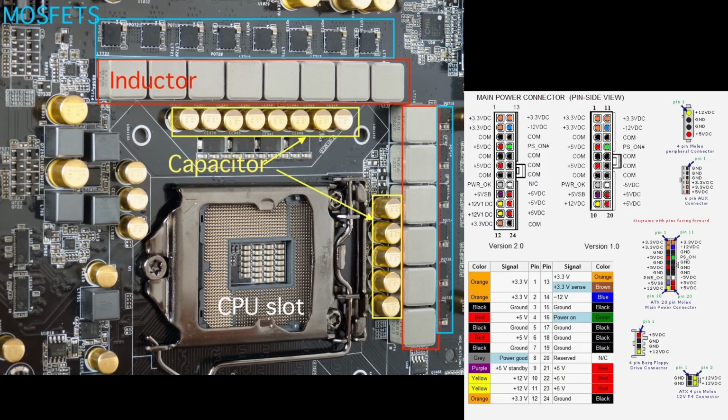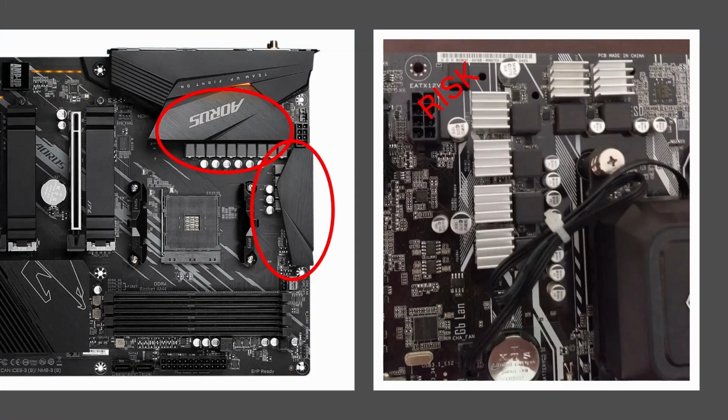The main power connector is also brought in through the PCB. You can see those on the right. The motherboard gets various power and ground signals coming from that, so it can operate at different voltages. Here, what we see on the left is the typical motherboard, right where those power modules are. The one on the left is provided with a heat sink, which helps keep those MOSFETs cool so it can provide a steady state voltage out to the CPU.